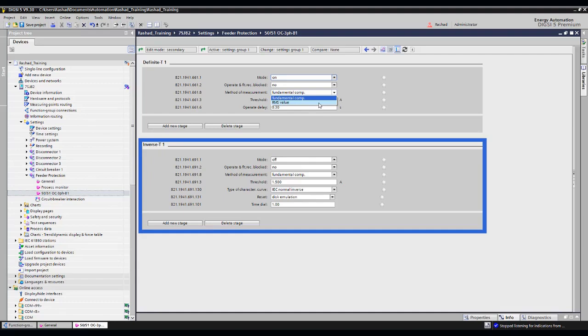So if you have loads, and you know these loads superimpose a set of harmonics, and you want to set it, you can't choose the fundamental, because at that time it works on the entire wave that includes harmonics, and therefore it might constantly be affected by errors. Is that clear? So, what should I choose?